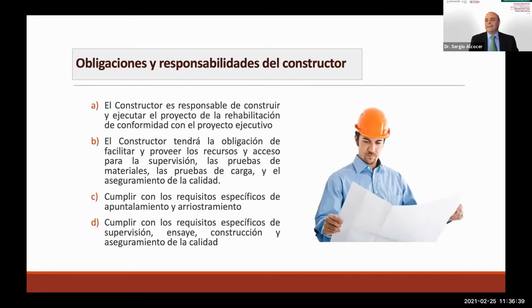And this is important because in refitting projects, we frequently take away structural elements that have the ability to withstand earthquakes, and thus we leave these buildings more vulnerable to side loads. And that is why the constructor must pay attention to framing and bracing the building as the project designer planned. If this doesn't take place, it will be important to get someone who knows the bracing techniques that are necessary, and also they will need to comply with the specific requirements pointed out for the supervision, testing, construction, and quality assurance.